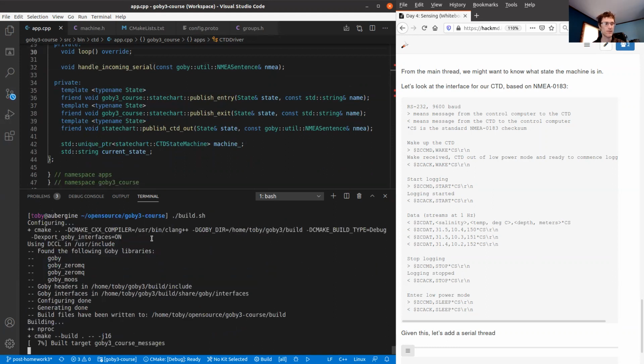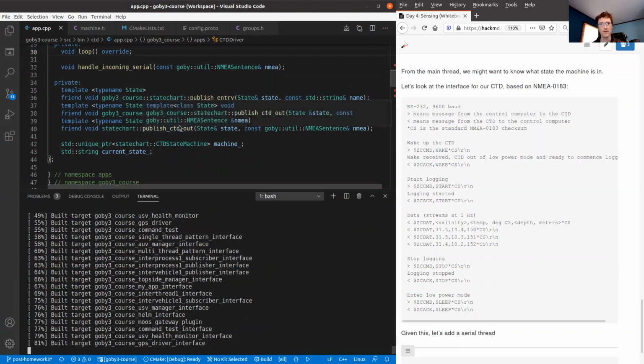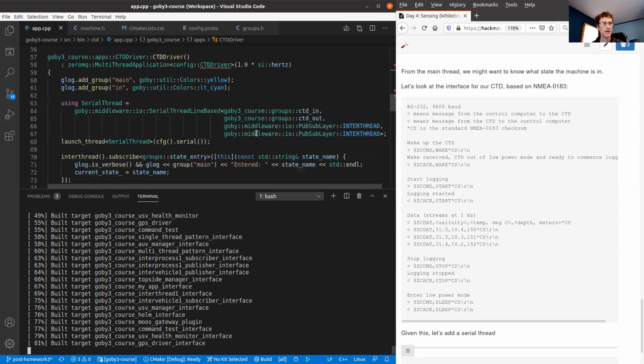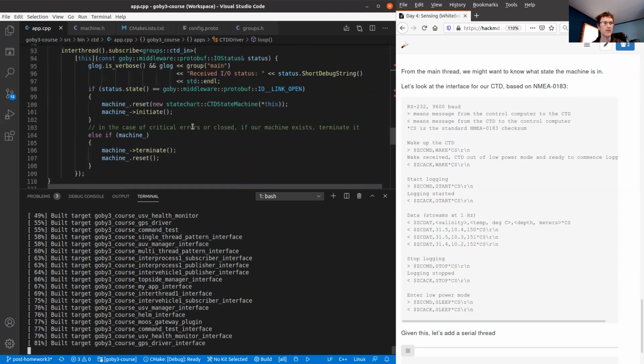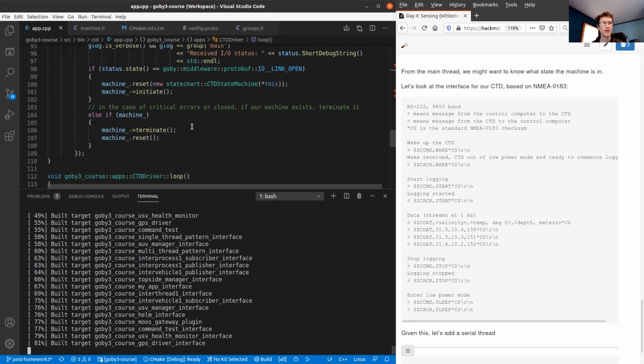And with a real sensor, you're probably also going to have to use a timeout and retry model, because sometimes the instrument isn't going to respond to your first attempt, but we'll ignore that for this course. It's something you'll have to figure out when you do this for real, depending on how cranky your sensor is.